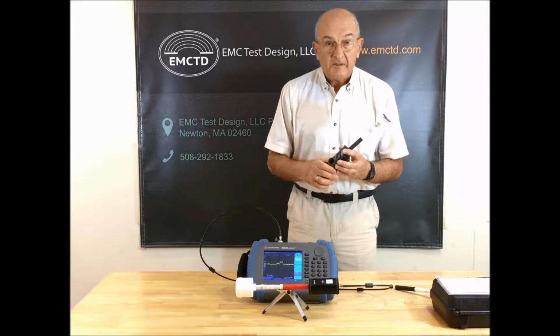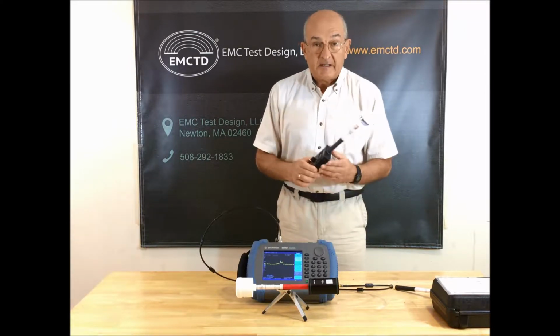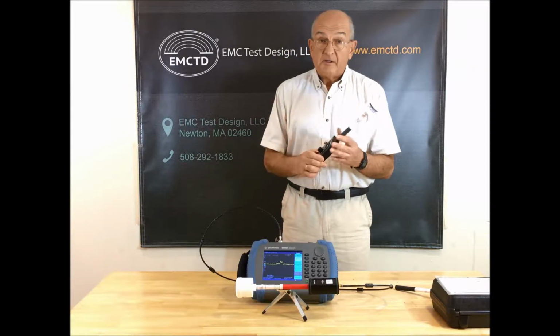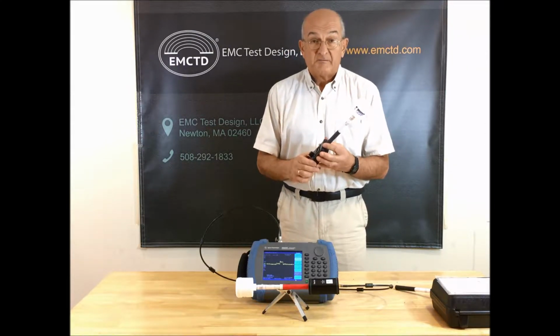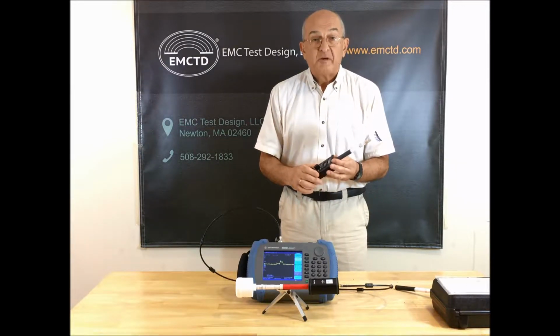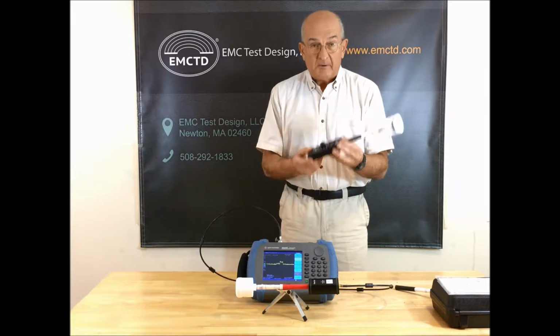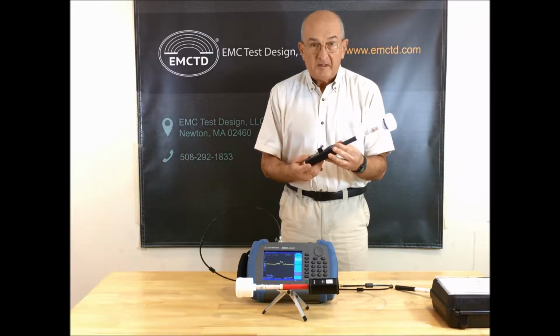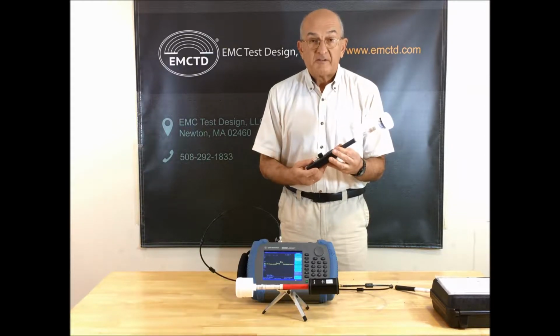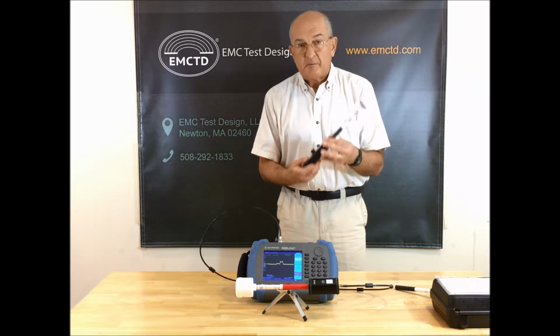The reason why you need to have such product as isotropic antenna is that if you don't know the frequency, or maybe signal of interest is surrounded by some other signals, maybe even higher amplitude, you will not be able to measure it with a broadband probe, because broadband probe will show you the cumulative field strengths independently on frequency, and you will never know which signal you're observing.